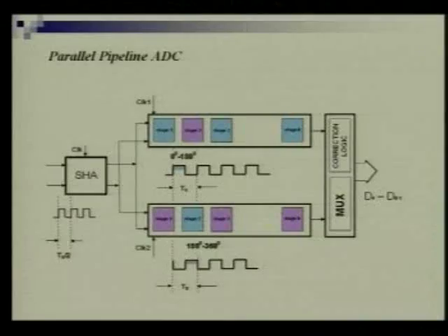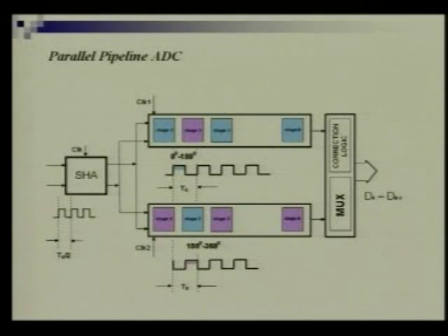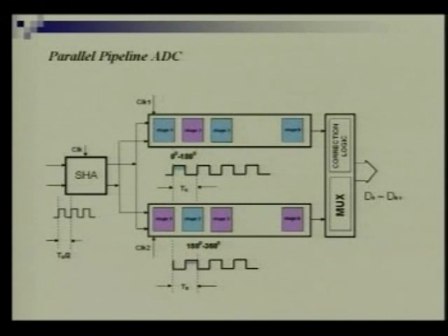Here, what we have tried to do is have one pipeline architecture, another pipeline, and some sample and hold. You are going ahead with the 2 stages, and you can do the clocking. For this blue part, you use 180 degrees, so you can sample them with 2 clocks. When this is the first stage, this comes in the next, using the same clock to drive both things. If you are using a single clock, that gives you another advantage: less hardware and also less power.